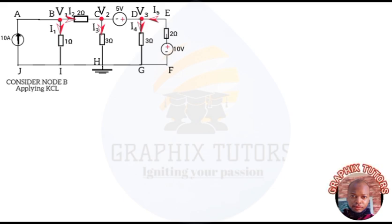Applying Kirchhoff's current law at node B. What does the law say? It says that the current entering the node is equal to the current leaving the node. Now if you look at node B, what current is entering node B? The 10 ampere independent current source is moving in this manner towards node B. So we'll put it down because that's the current entering. That is the only current entering node B, equal to the current leaving.